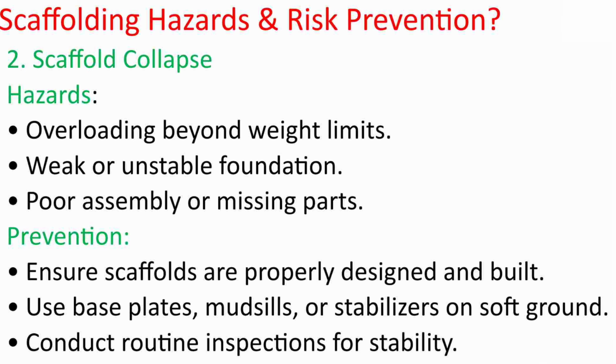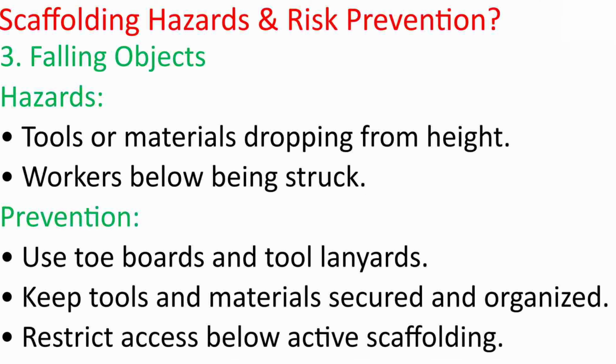2. Scaffold collapse. Hazards: overloading beyond weight limits, weak or unstable foundation, poor assembly or missing parts. Prevention: ensure scaffolds are properly designed and built. Use base plates, mudsills, or stabilizers on soft ground. Conduct routine inspections for stability.